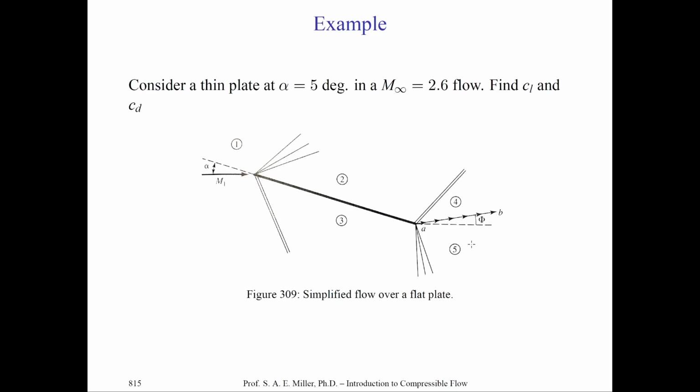Now, what happens between 4 and 5? Indeed, in this particular case, the static pressures are equal, and this is why an oblique shock wave forms and an expansion wave forms with equal velocity vectors. And you'll notice that after the trailing edge, in the wake of this flat plate, we indeed have a non-zero angle in degrees, capital Phi.